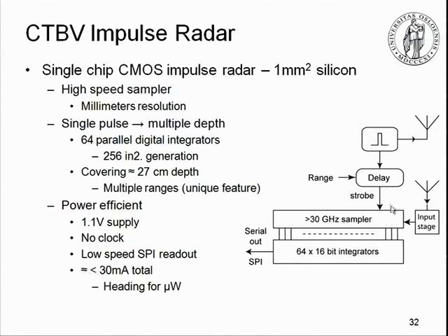Now, we do a little better with these integrated radars, because when we receive the signal here, we have this input stage, which is basically a thresholding element. And instead of just sampling, since we threshold, we're binary value here, but still continuous time. There's no clock. So all this is binary value continuous time. We have zeros and ones here. And zeros and ones is something we're really good at treating at high speed. Again, technology. So we can sample it.